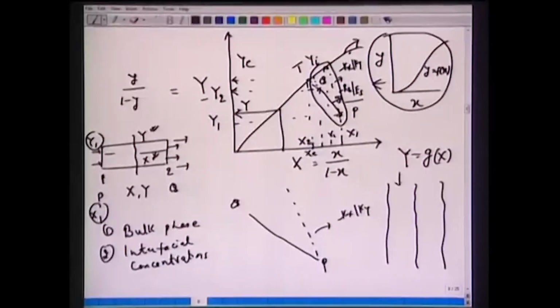We have this co-current, two phases, the gas and the liquid, getting in here. We have the bulk phase, which drops to some interfacial concentration. Then we have the bulk phase concentration in the liquid phase. So we have y, we have x, we have yi, we have xi. Equivalent to this y, we can have x star. Equivalent to this x, we can have y star. And these points can also be marked here.